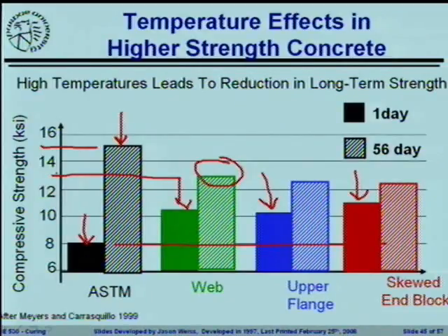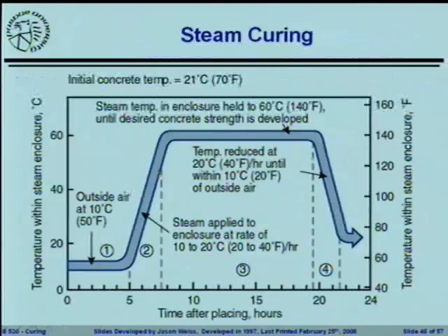Now this starts to become a big problem, because if you're designing this concrete to be able to withstand 15,000 psi, and in the field it never gets there, you have dramatically under-provided what the concrete is going to be able to do in the field. So temperature management is really a major issue when you start to look at concrete elements.